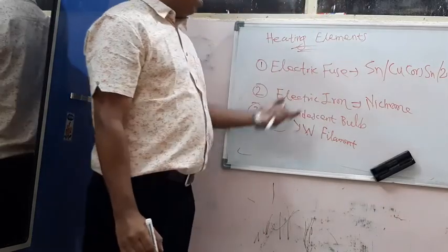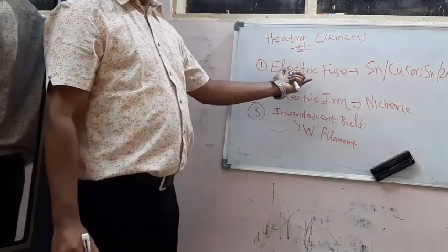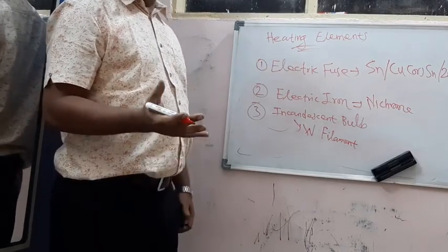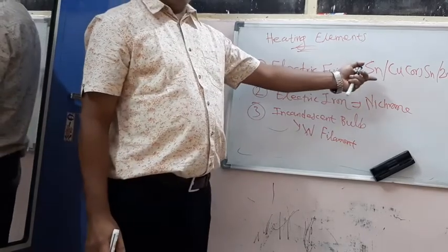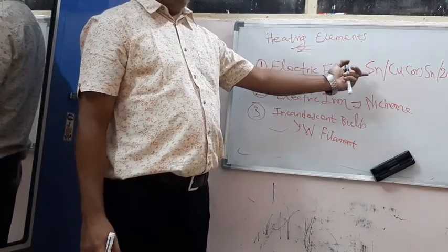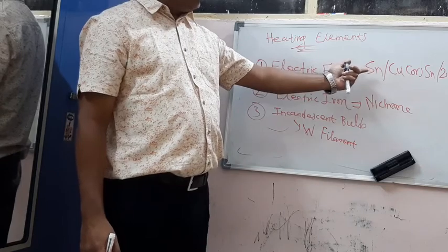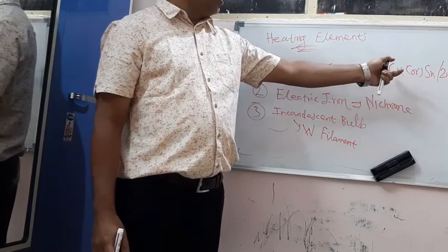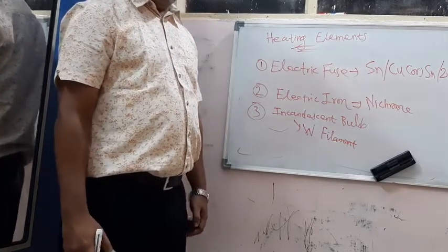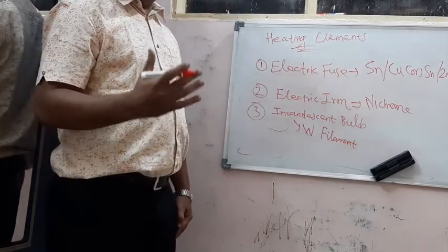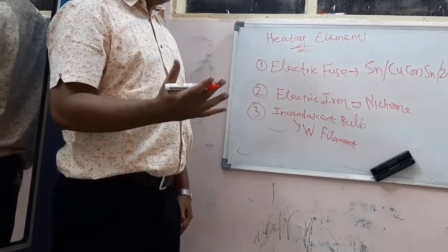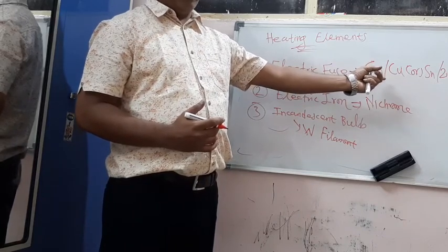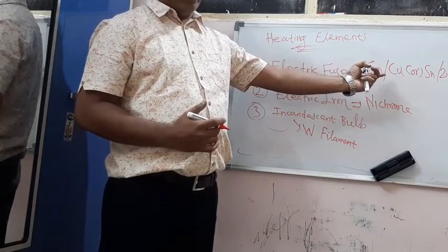The role of an electric fuse in any circuit is that when a higher amount of current flows in the circuit, it acts as a circuit breaker. Because of higher electric current, more heat is generated in the tin plated copper wire. When it reaches a particular value, it starts to melt because of its low melting point, and breakdown takes place.